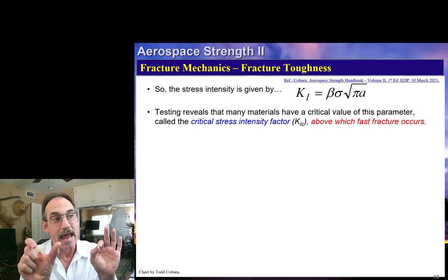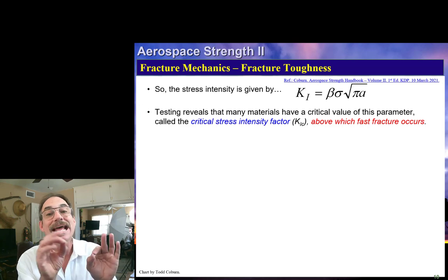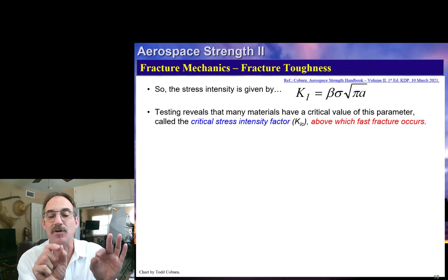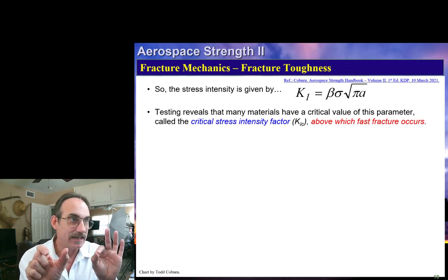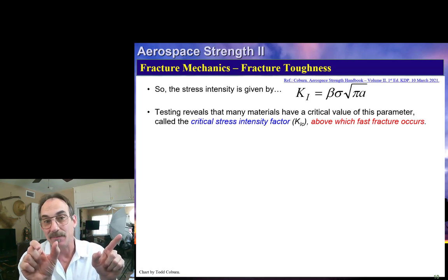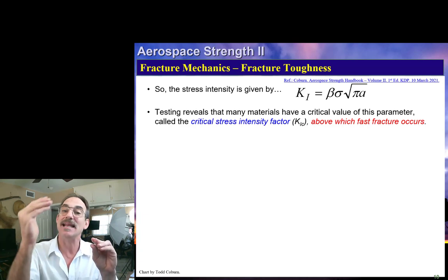with your K. As your crack grows through the part, your K1 is increasing by the square root of that, right? Not only that, your K1 is increasing because the A is increasing, but your beta is going to be changing because that A over B ratio is increasing. So you're kind of getting a double effect.